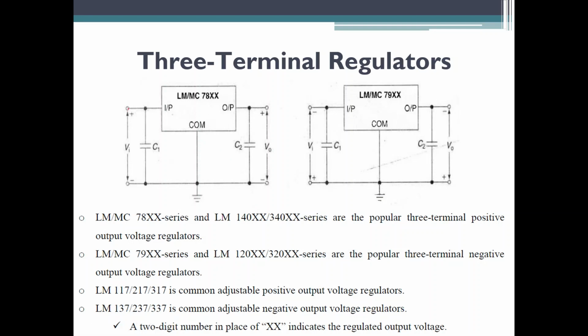Whatever input you give, the output from the filter, you need to give the DC from here, and that DC will be filtered by this capacitor. In fact, the capacitors that I have connected here will basically be functioning, or helping me in removing the ripples, and this is the one which is going to smoothen it, or make sure that variations in the output will not vary the power source.